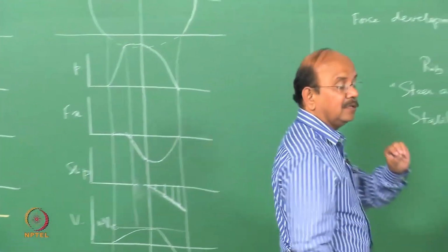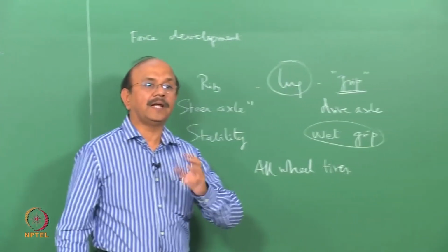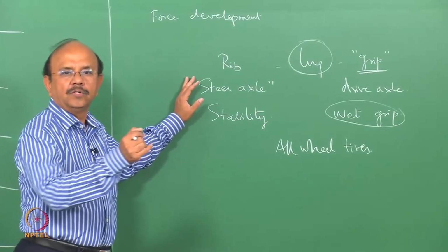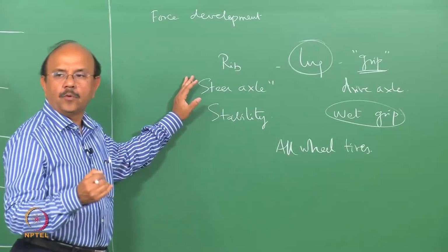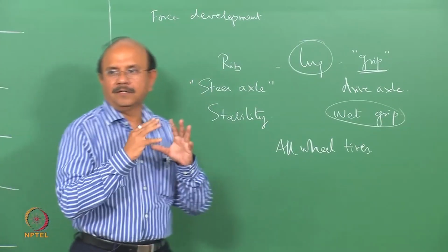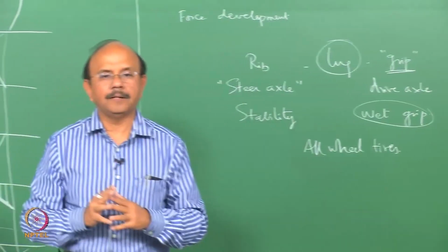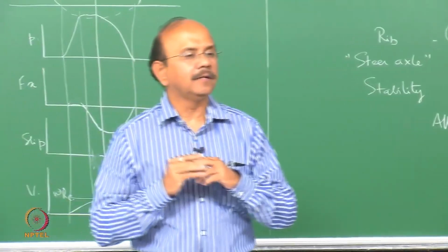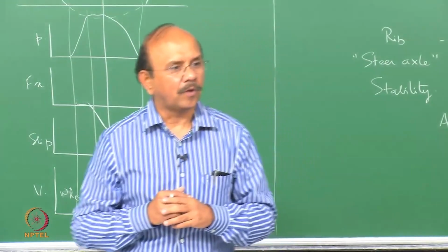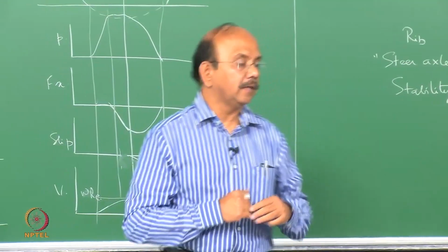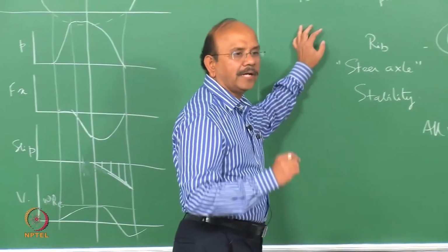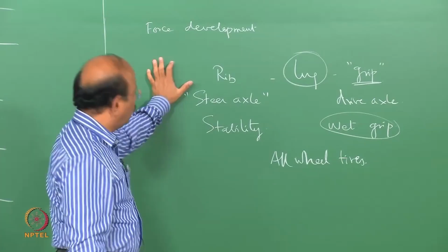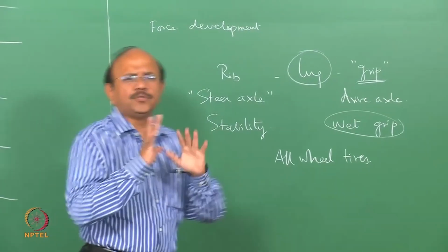Now there is a lot of research going on, and there are tires where you have a rib-like tire with a lateral groove in order to carry this water. The grooves are very strategically put. There, a lot of analysis is done. A fluid structure interaction analysis is done in order to understand how the water flows. These grooves are put so that the water is carried. Clear?